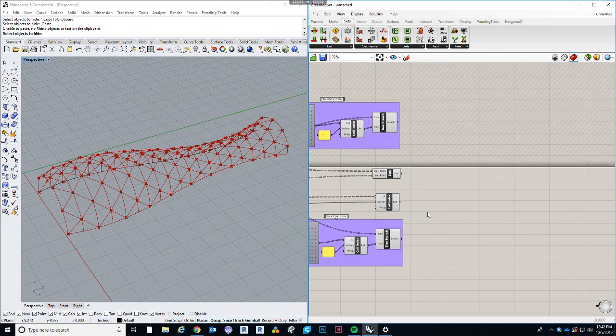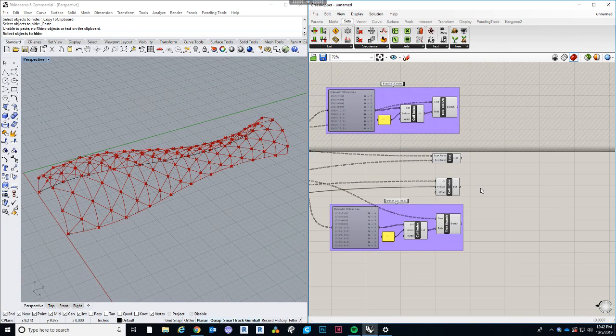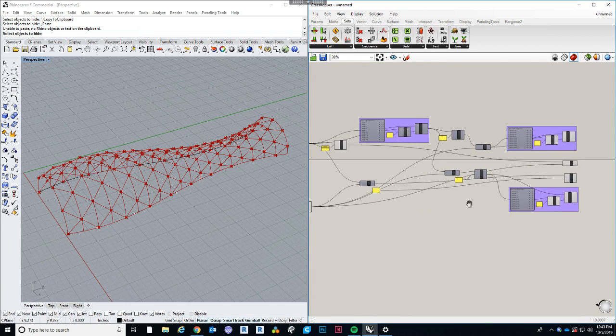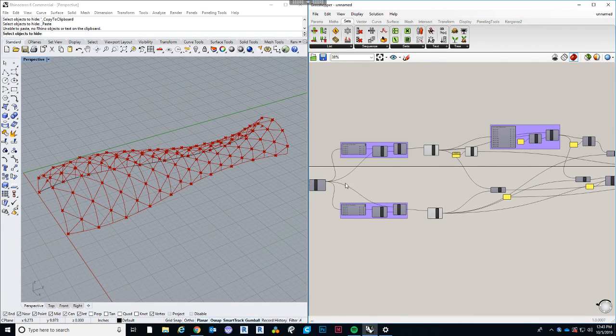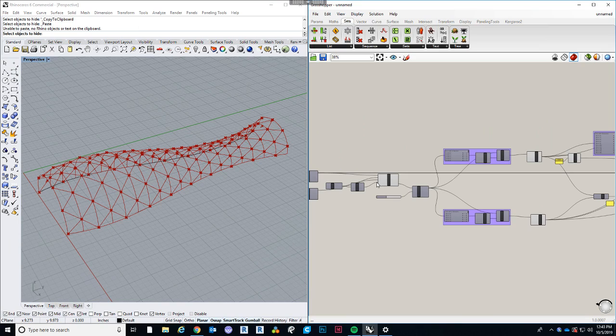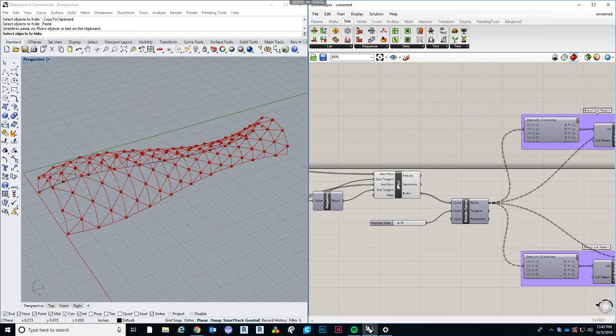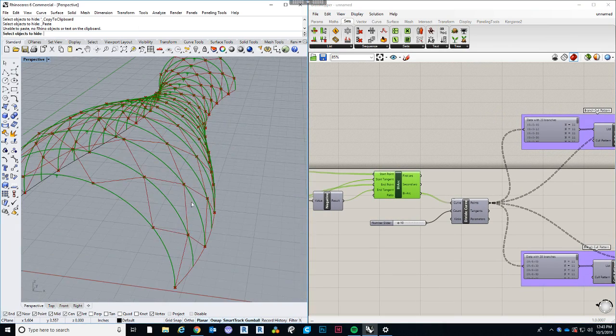And now I want to create surfaces. And before I create surfaces, the panelized triangulated structure, I want to go back and I'm going to turn some things off and turn some things down. So first thing I'm going to do is turn the biArcs off, because when we start creating these triangulated surfaces, it's not going to be rounded anymore. It's going to be faceted.